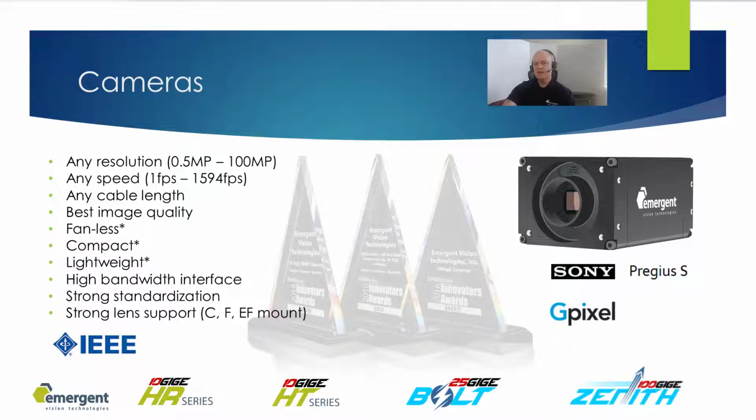Consider the impact of a camera-based fan in the application. Noise from the fan is disruptive for audio recordings within the volumetric capture space. A fan is also a sign of higher power consumption, so consider that within recordings, if a fan is turned off during the recording, the camera will heat up, possibly to the point of overheating, but at least to the point of creating a noisier image. This is one point that can limit recording times in some systems.